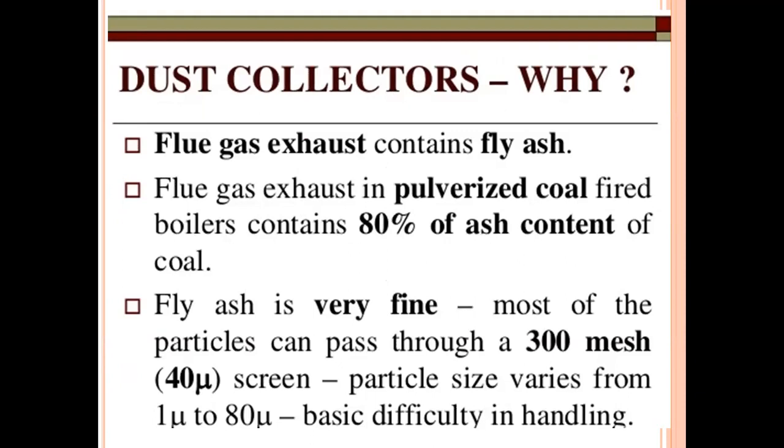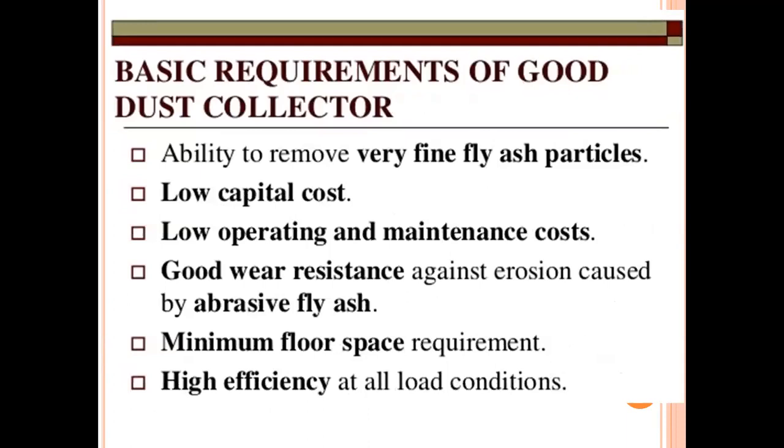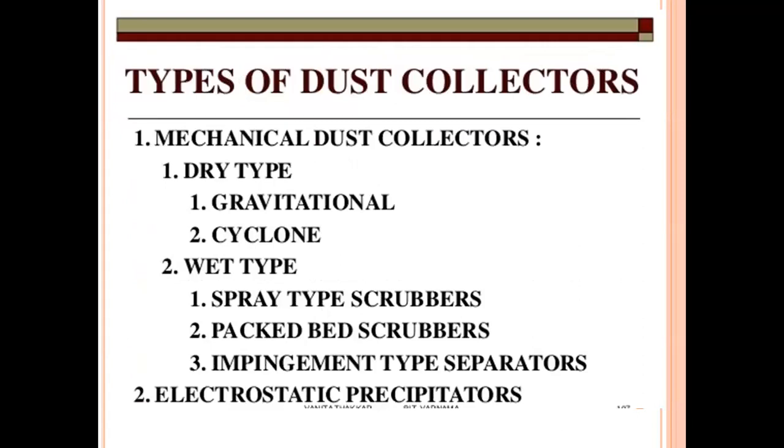Basic difficulty in handling. Basic requirements of a good dust collector: ability to remove very fine fly ash particles, low capital cost, low operating and maintenance cost, good wear resistance against erosion caused by abrasive fly ash, minimum floor space requirement, high efficiency at all load conditions.